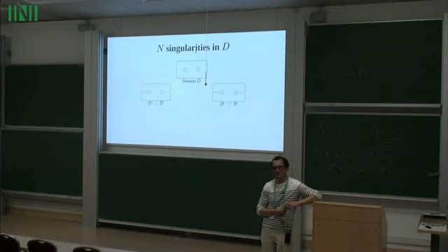Of course, it will have an effect on the homogenized matrix. And then you optimize over all possible shears under one linear constraint, that the strain matrix field comes from a single displacement. To me that looks, at first glance, a bit simpler. Is there a reason for not doing this?